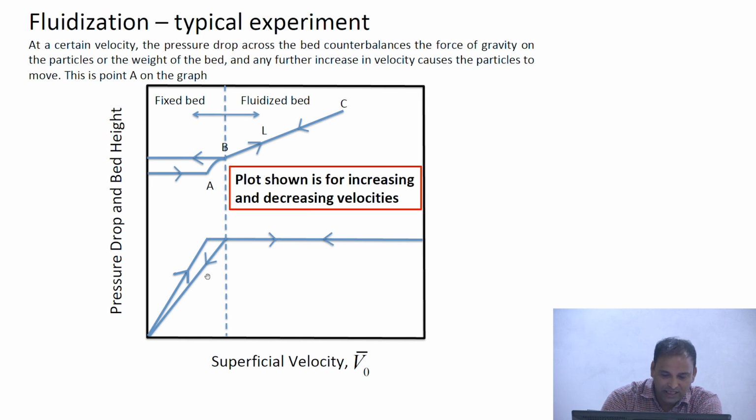And it's not this point, because the superficial velocity corresponding to this point depends on the way you pack stuff. However, the return cycle always gives you a bed of a porosity which is very similar whether I use smaller particles or larger particles. As long as I work with the same particle shape, you'll always end up with epsilon m, the porosity at minimum fluidization, which is very close to what we discussed in the last class, the typical value of 0.36.